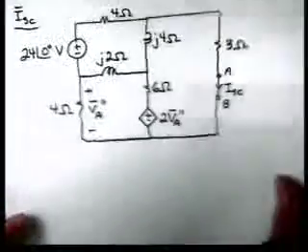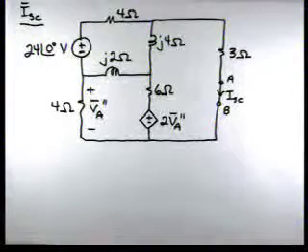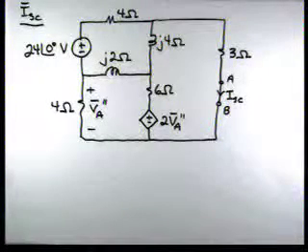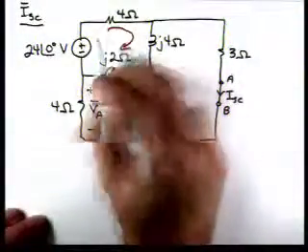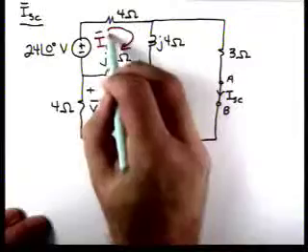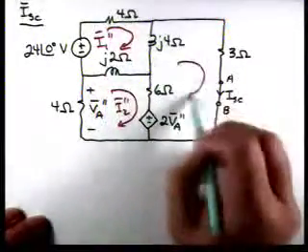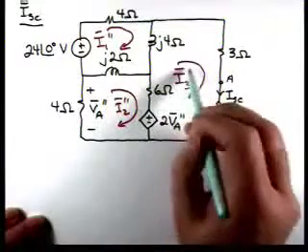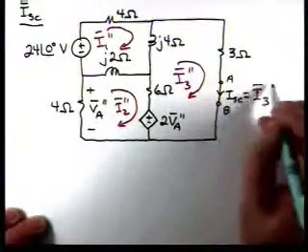So now we're going to take our circuit and place a short between terminals A and B, and again we'll use mesh analysis. If we notice, I short circuit will be I3 double prime.